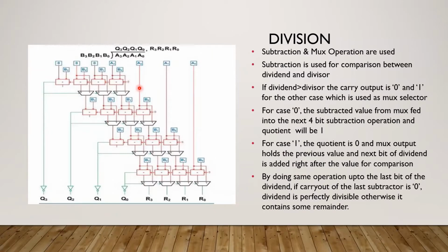I am 1706193. I am going to describe the division operation of our project. For this operation, we used four 4-bit full adders and four 2-to-1 muxes. Now, if we look into our block diagram shown here, the adder is performing the subtraction and the connected mux is allowing which output should be passed to the next subtractor.